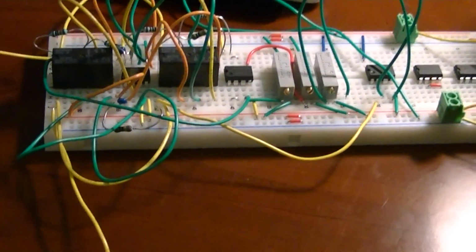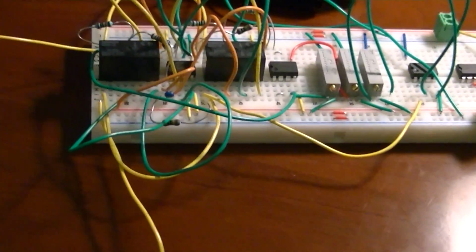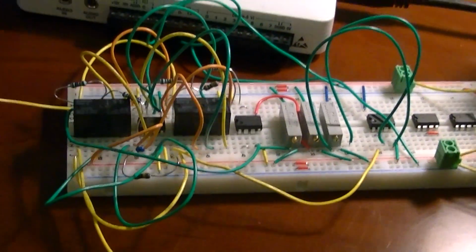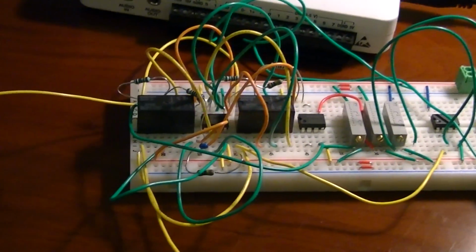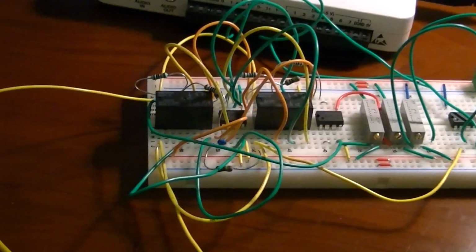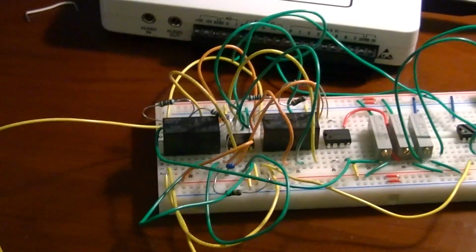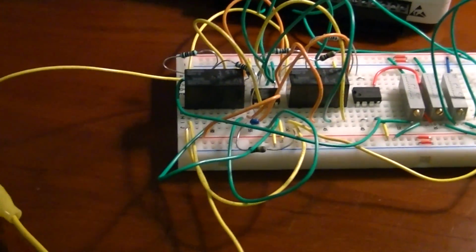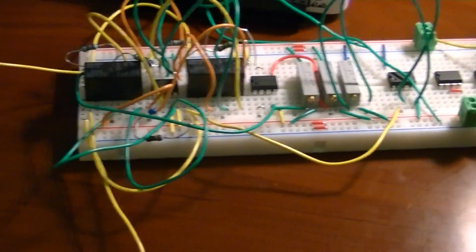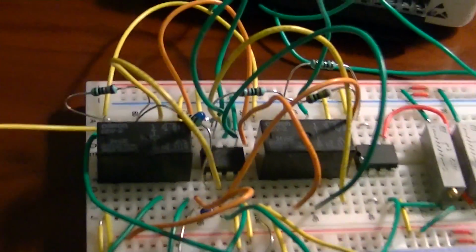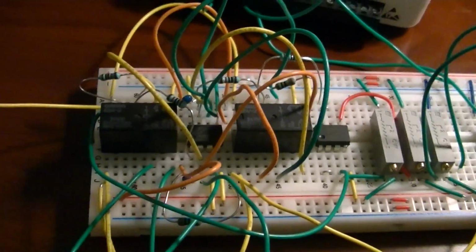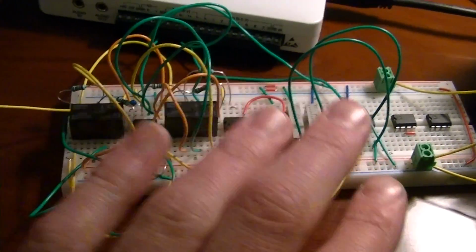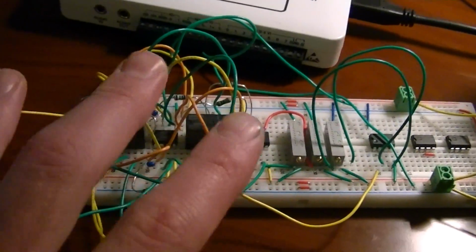Now, most people think computing is inherently digital. It's not. It's really analog, meaning there's a continuous range of voltages, pressures, temperatures, what have you, and then these are put into regions. We'll say if it's less than 1 volt, that's 0. If it's more than 4, that's 1, and that's how digital works. But it raises the question, can you compute in a different way, using the analog voltage itself to represent the quantity? And that's exactly what this does here. These are voltage dividers with the follower amplifier and 2 numerical integrators.